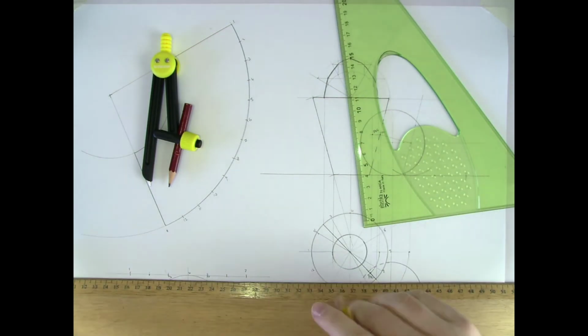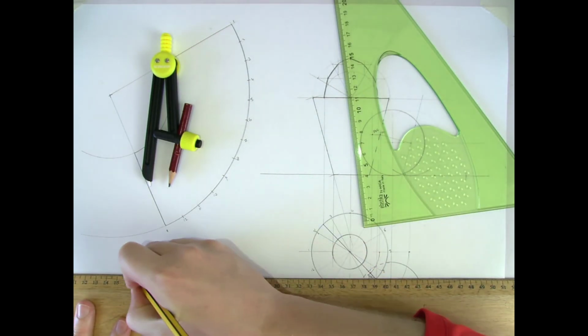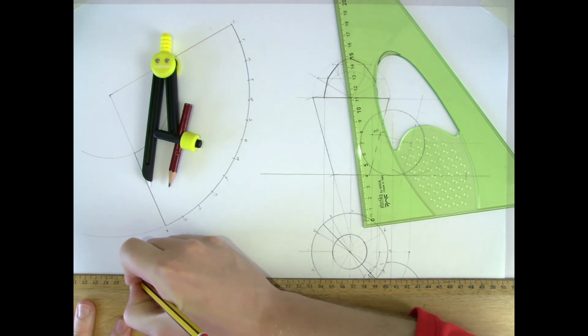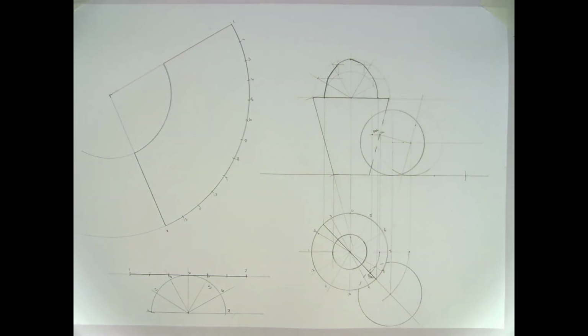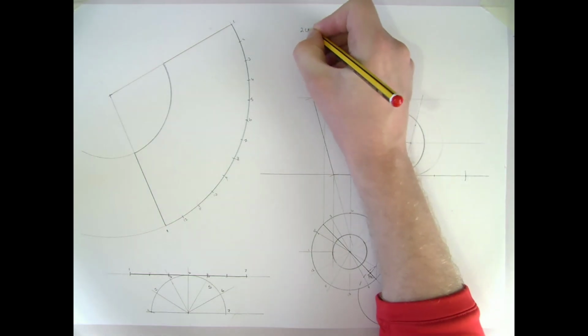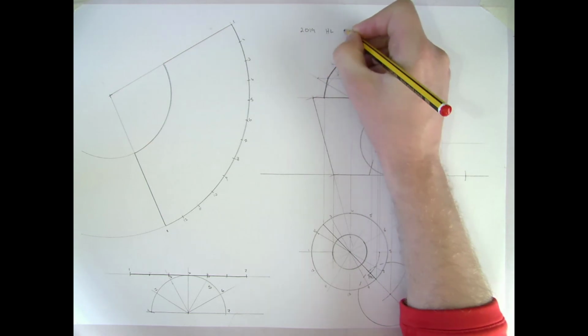So the development of the semicircle is this line here. All that I've taken is I've measured the distances from 4 to 3, swung that up here, from 3 to 2, added that onto it, from 2 to 1, added that on. Same on the opposite side, from 4 to 5, measured that here, from 5 to 6, added that on, and from 6 to 7, added that on also. So that completes the development of part C. So this also completes the question. It is the 2019 higher level question 4.